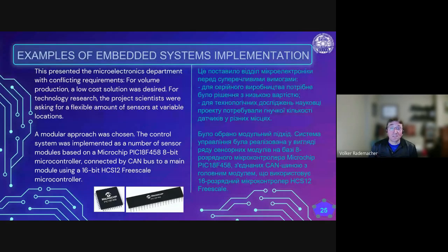If you don't understand any of that, the basic line here is that the CAN bus is very good for real-time tasks and for transferring measurement results. It is very bad at transferring large amounts of data, and for that purpose, USB or Ethernet is much better suited.